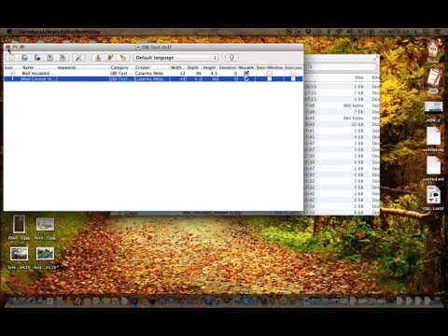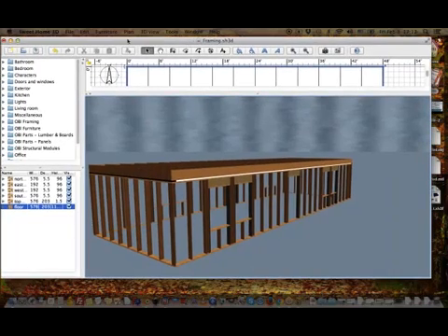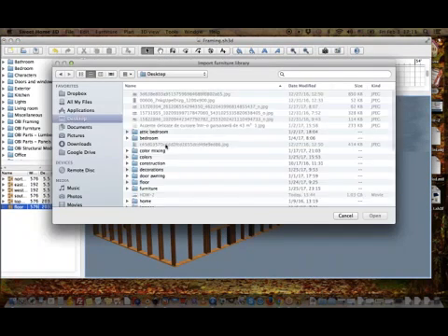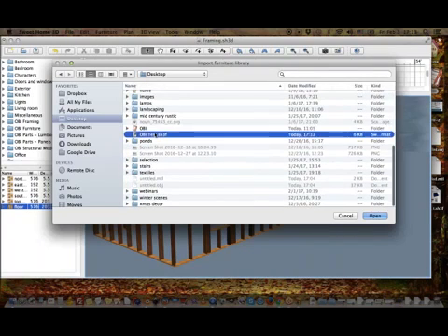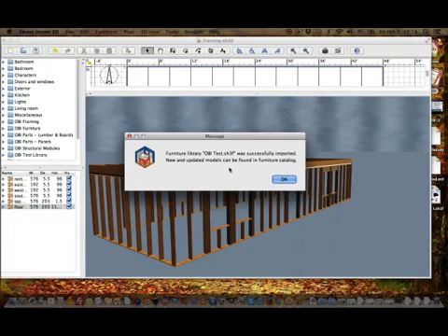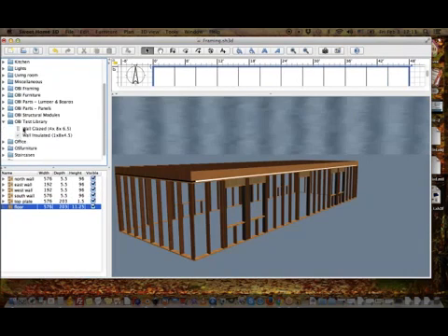All right, so I'm going to save it on the desktop and call it OBI test. Okay, so that's it. Now I go back to Sweet Home 3D, and I'm going to do furniture import, no, sorry. It's a bit late in the day. Furniture, import furniture library, and where's the library I just created? I called it OBI test. Here it is. I just created this file, and I open it, and it tells me it was successfully imported, right? So now I go here. Oh, and here's the OBI test library. And here are the modules I just created, I just added to this library.